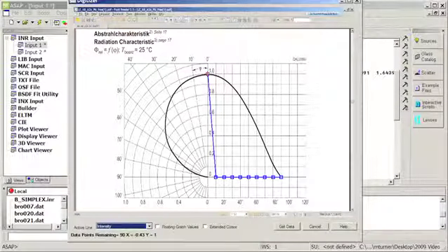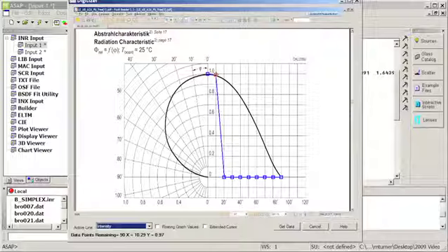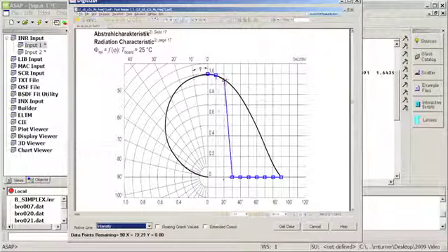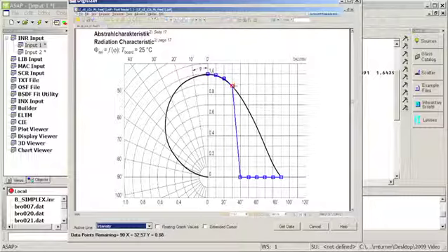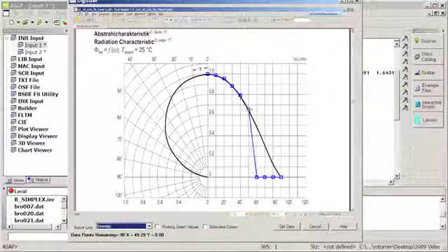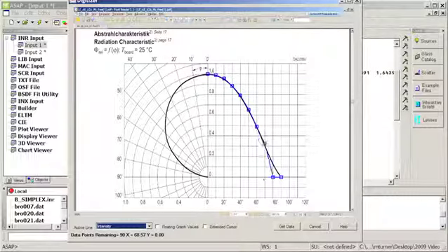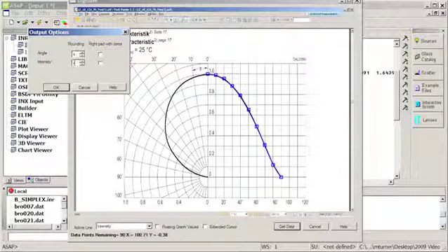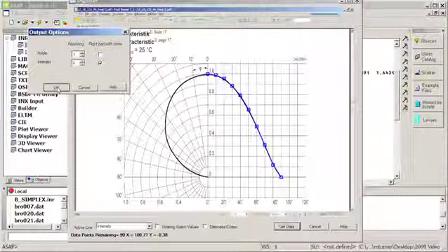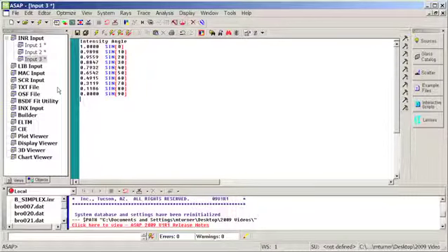And again, we'll simply take the data points and adjust them to match the curve. And there we go. And again, we'll just get the data for the intensity curve. For my angle, I'll only use 1 decimal place. For the intensity, I'll just stick to 4, but right pad with zeros to get uniform data representations, and click on OK. And as you see, we have our file with the intensity as a function of the sine of the angle.